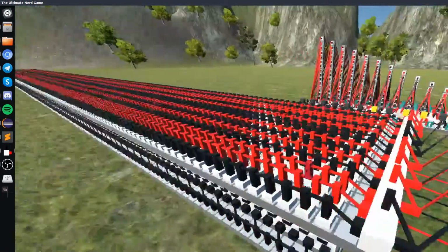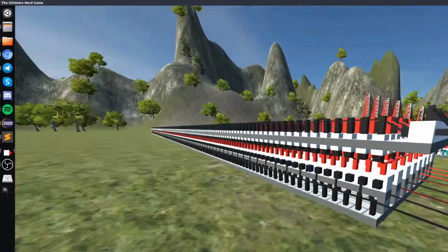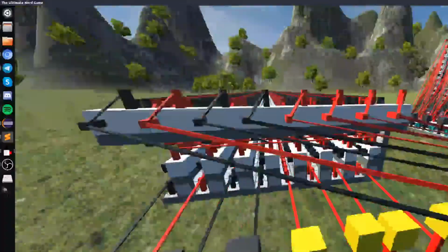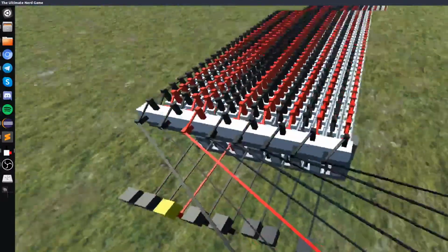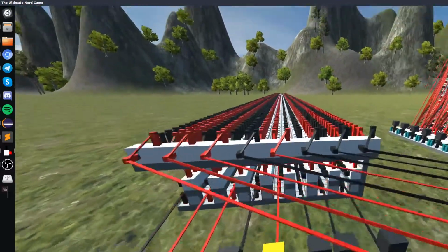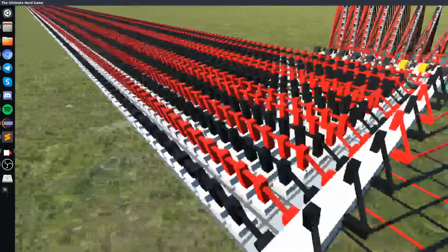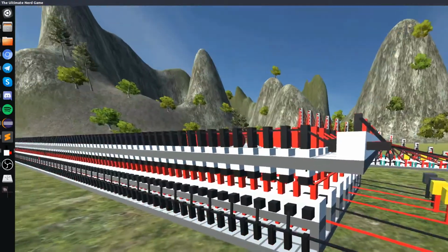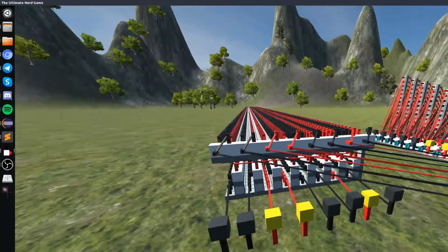I can freely define the size in terms of bit width and amounts of addresses. There's a limitation though that you need more bits than address bits possible. That's because the decoder is right on top. I could have more bits than possible addresses. That's totally fine. Like 4-bit addresses and 8-bit data, but not the other way around, for the simple reason of the size here. The wires attached directly to the inverter there. So this is the design I had in my mind from the very beginning.